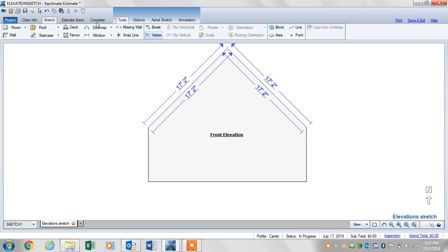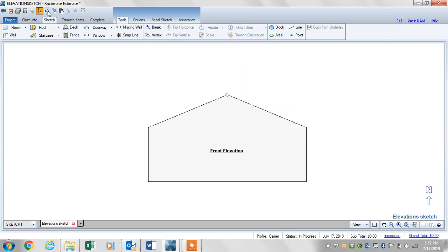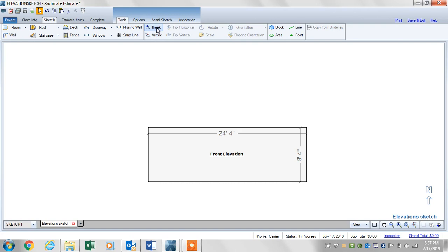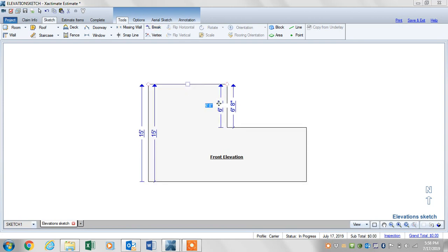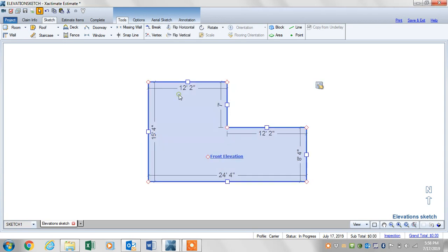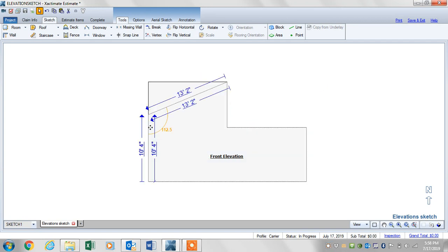So what I like to do, which I think works better, is to use your pull bar and bring it down. Let's get that in the center again. Let's say this is 7 feet right here from the top peak of the gable to the wall height. So I left click, hold this up, and bring this to 7 feet. Now we know that this pull bar, this handle, would be 7 feet. So I take this handle and draw it down.